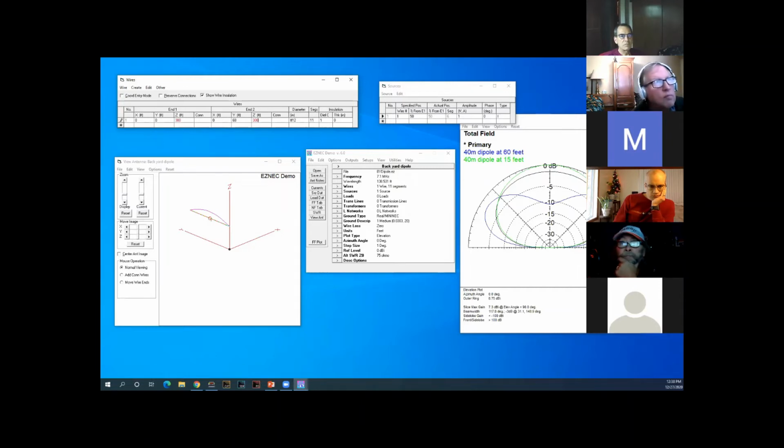So again, it's an advanced topic, but I could show you the probability of where these signals are coming in, which I did in the article in QST. I showed basically you can design your antenna based on the probability of where the signals are coming in. Say the highest probability of signals coming in from Europe on 40 meters might be 20 degrees. Well, let's design an antenna.